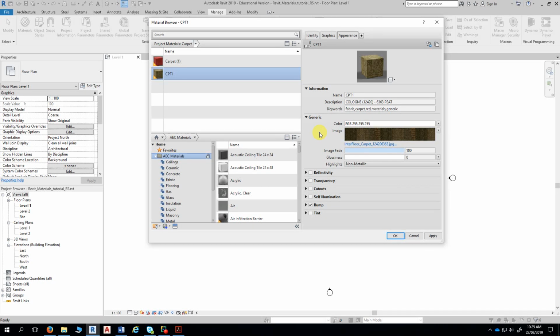If you're creating a material for a brick wall, for instance, and you know standard bricks are 230 long by 76 high, then if you have a sample photo of a portion of a brick wall, you then have to have a look at scaling that image to make sure that you get the correct number of bricks in a certain height of wall.